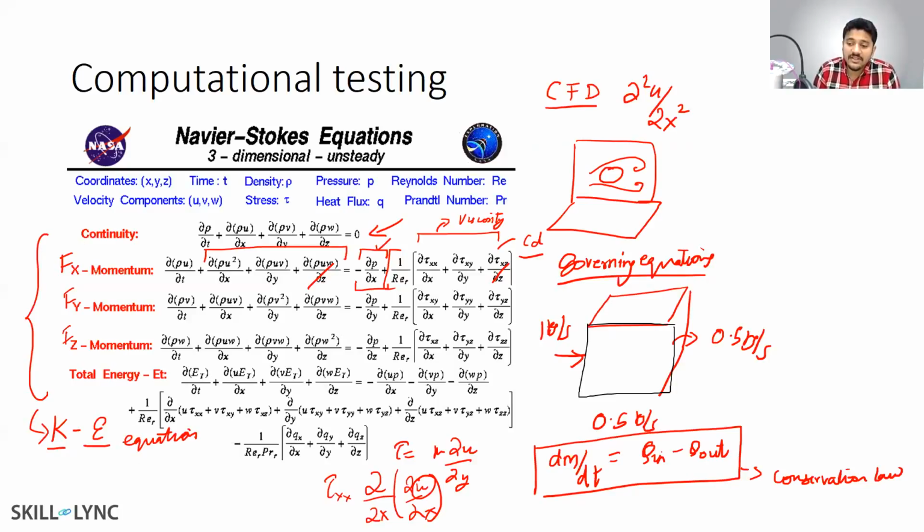Shahzad, shear stress has 6 unknown terms. Well, you need to understand the shear stress depends on the velocity, right? Tau depends upon velocity. So it's not 6 unknowns. If you know the x, y, z components of velocity, then you can determine your shear stress. We cannot consider all turbulence scales, so we model. Can you explain a little bit more? Why cannot we consider all turbulence scales? We can consider all the turbulence scales for accurate understanding of turbulent flow, that's completely wrong.